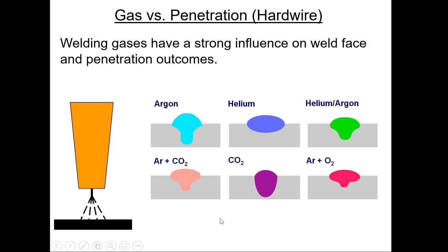Now, I borrowed this from the MIG welding world to show how mixed gases affect the welding penetration zones and the welds based on their mixes. Pure inert, pure inert, pure inert mix. And this is what we commonly do, and what you are commonly doing on the shop floor when making parts. That's argon and carbon dioxide. Most plants are 90-10.